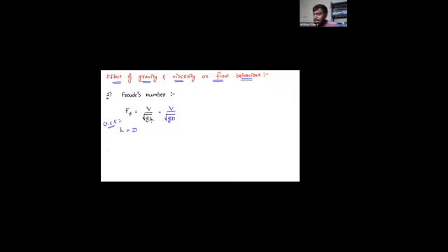So Froude number, and now the L is nothing but D. Why do we take D, sir? D is nothing but the average depth of flow. When we analyze, are we taking maximum depth or average depth? Average depth. That average depth is nothing but the hydraulic depth. And you know that in the case of a rectangle, D is equal to y.